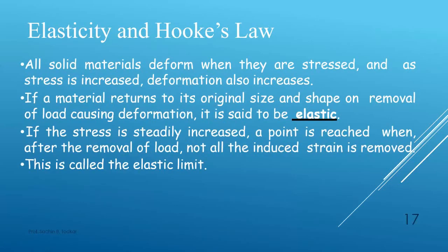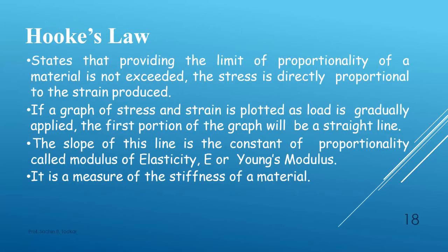Now, elasticity and Hooke's law. You have seen what elasticity is, or what the elastic limit is. Hooke's law is very important to define the relation between stress and strain. Hooke's law states that, provided the limit of proportionality of a material is not exceeded, the stress is directly proportional to the strain produced.